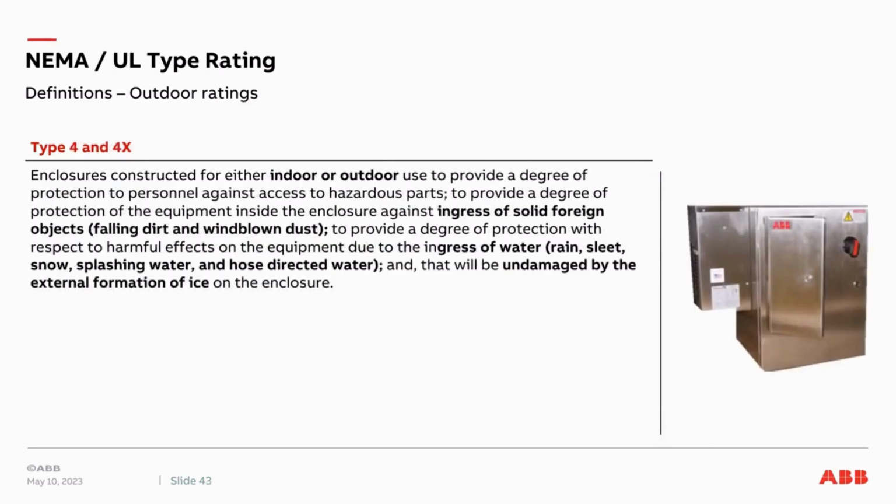Looking at a Type 4 or 4X enclosure, the enclosures are constructed for either indoor or outdoor use as before. They will protect you against the ingress of solid foreign objects, falling dirt, wind-blown dust, and personnel, but their advantage is protection against the ingress of water, rain, sleet, snow, splashing water, or hose-directed water, and they will be undamaged by the formation of ice.